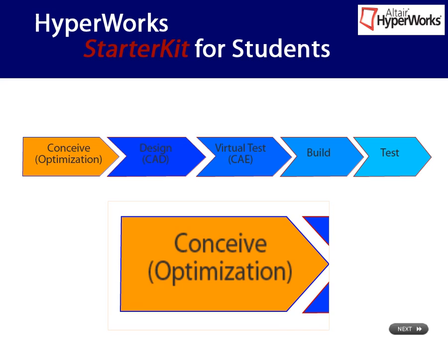Up to this point you learned how to set up a linear static analysis. The results of such an analysis essentially provide you with information about displacements and stresses indicating whether failure will occur or not. If failure of the component is likely to occur, corresponding actions follow. Most of the time, material is then added in a step-by-step approach until the part performs in the desired way.